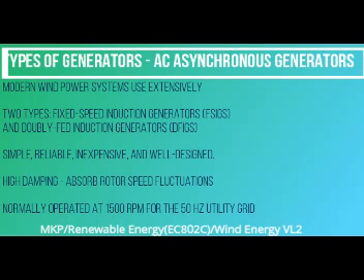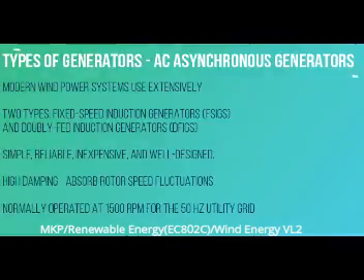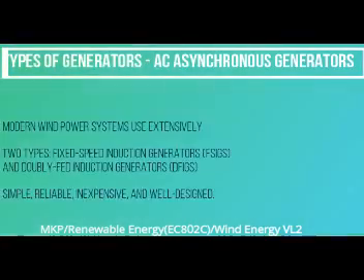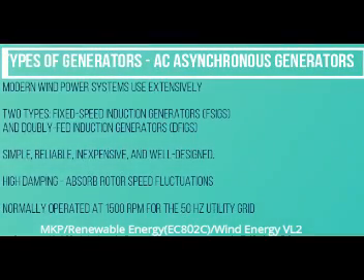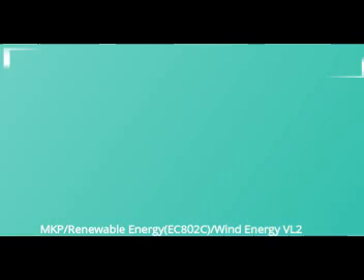These generators have a high degree of damping and can absorb rotor speed fluctuations and drivetrain transients. In the case of fixed speed induction generators, the stator is connected to the grid through a transformer and the rotor is connected to the wind turbine through a gearbox. These generators were normally operated at 1500 RPM for the 50 Hz utility grid along with a 3-stage gearbox.